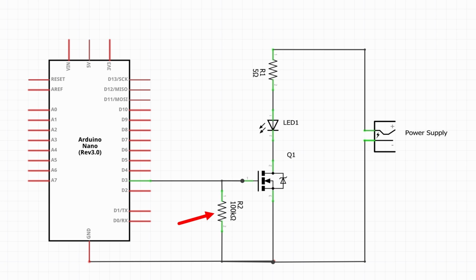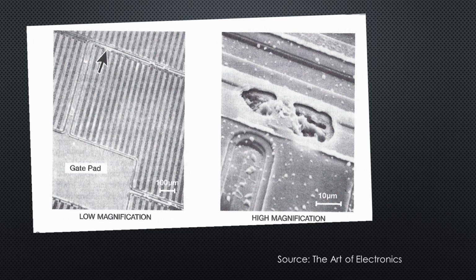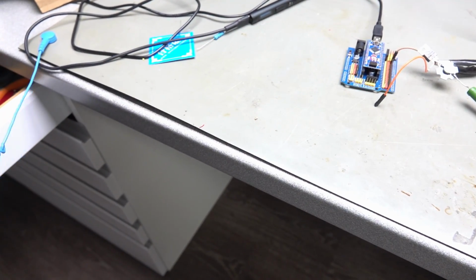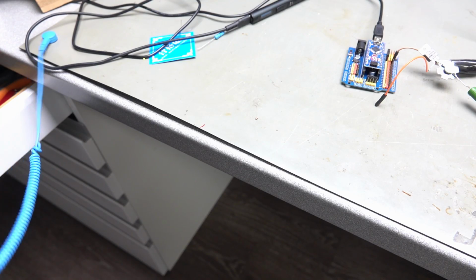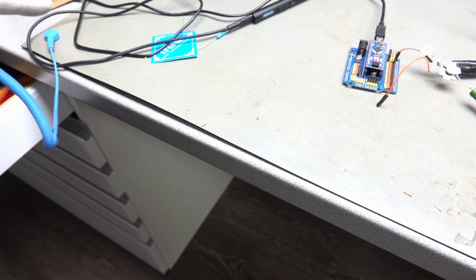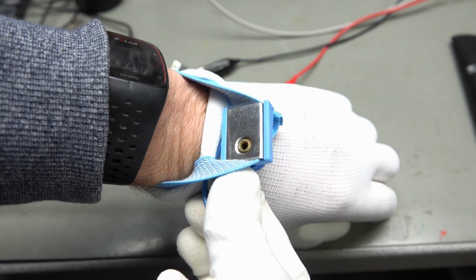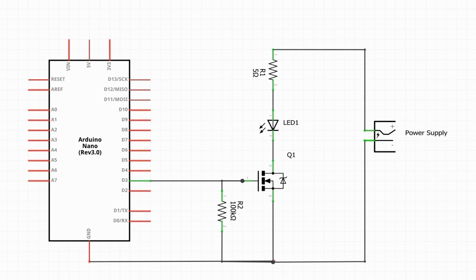This incredible feature has an important disadvantage. Small charges can destroy the isolation of the gate. The FET is then ready for the wastebasket. So pay attention if you work with FETs. Never use carpets. Use such an ESD mat on your desk and connect your body with the earth with such a band. There is one more important thing we have to know. Most FETs need gate voltages of more than 5 volts to switch completely on.